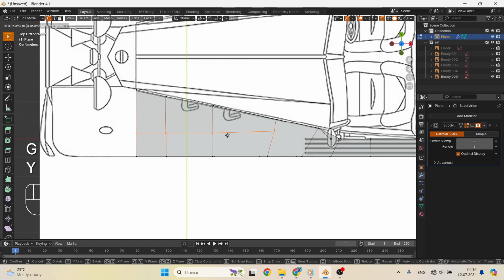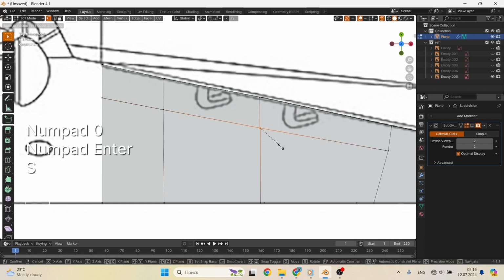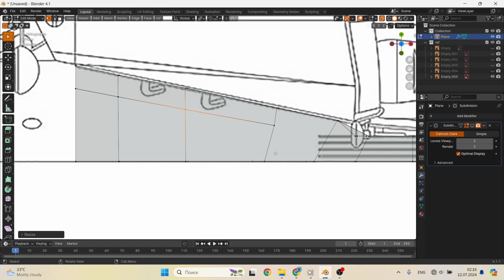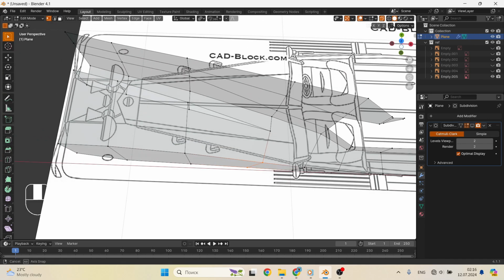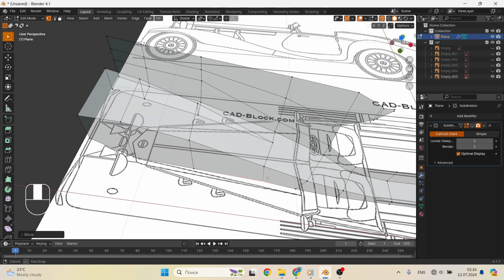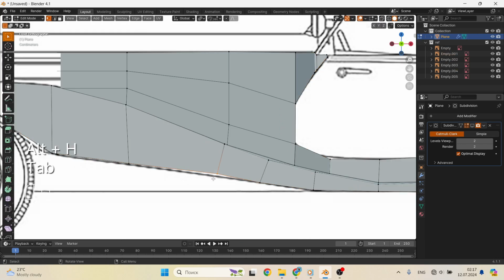2. Use as few polygons as possible. When you subdivide a mesh with the subdivision surface modifier, you don't have to worry about sharp corners in your object anymore, because they will all be smoothed out. In the end, no one will see the original low-poly model. Do you really need to use a cylinder with 32 edges, or can you get by with 6 by adding the subdivision surface modifier to level 2? Keep your models as simple as possible. If the polygons don't serve a specific purpose, they should probably be removed.